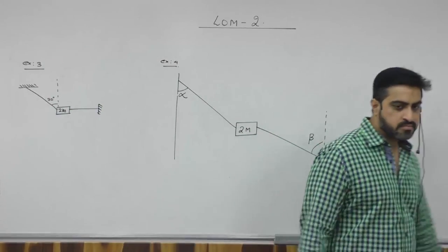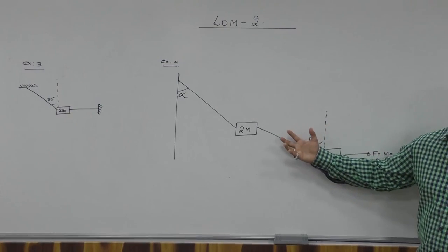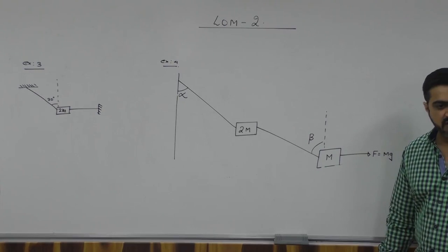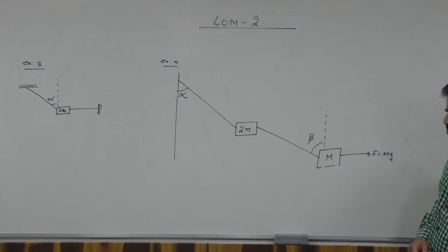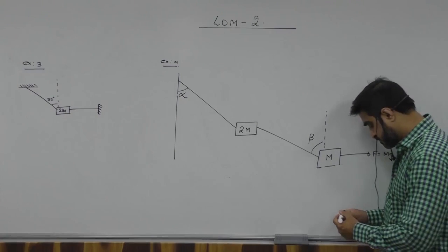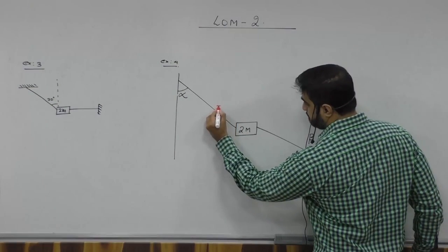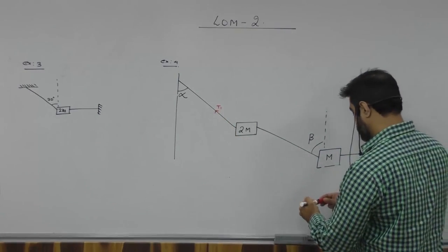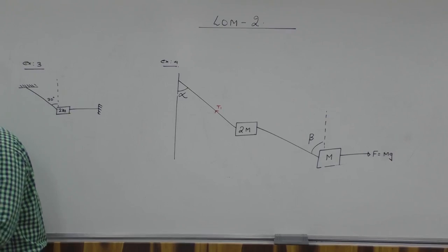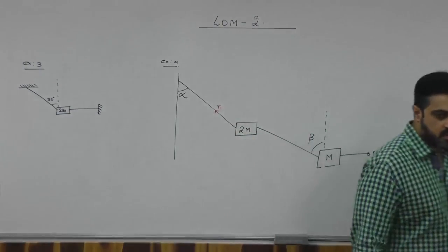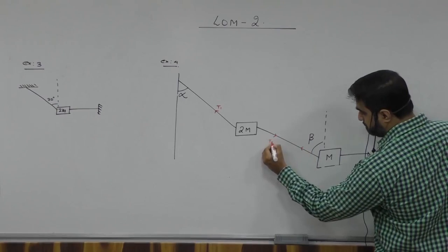This. I'll show you we can't use Lami's theorem over here. Lami's theorem is only valid for 3 concurrent forces at a given point. How is this going to be? Can I say the tension over here in this string, let it be T1. T1. T1. And the tension over here in the string, and the string is different, it will be T2.